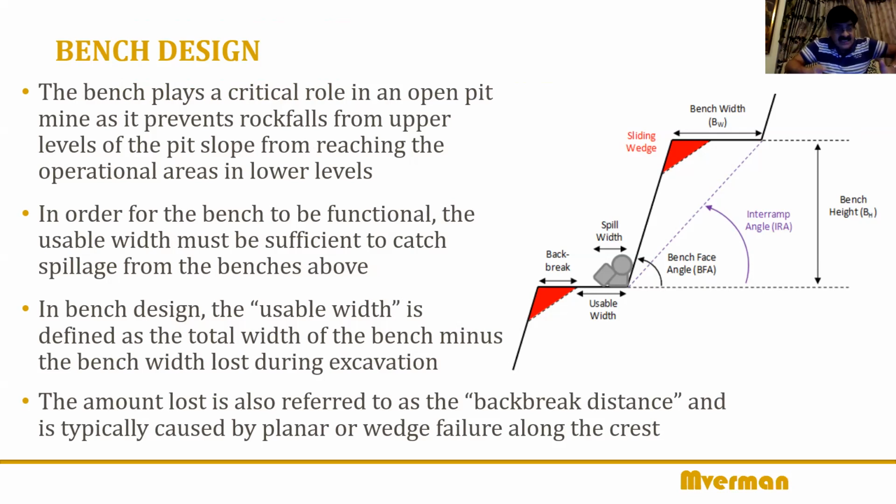And so the whole focus is there. Okay, so there the operation is going on at the bottommost level, they're extracting and all the things are being done. You do not want anything to reach there, any fall to reach there. So these benches arrest these slides of fall. But the bench has to be functional also.